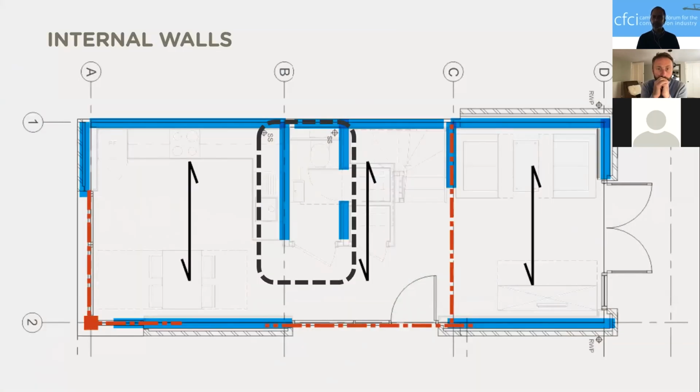Our initial houses had some stability walls to the stair. We had very little wall on the outside face to make the house stable. Internal stability walls worked quite well, and we do them a lot on CLT buildings, but with a module you've got to hold that down somewhere. That means access hatches, and it means someone trying to get their hand into a foundation in a place they have difficulty accessing. So the problems and the logistics can very quickly escalate.